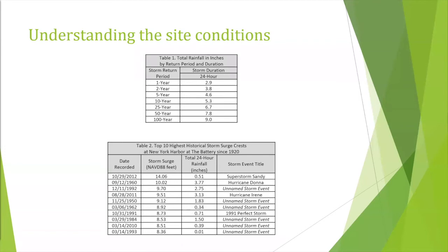So we understood that, but we also knew the price tag that goes along with that. They were talking about a 12-foot high wall around a 100-acre property with 8 different gates, which were floodgates. And then they were talking about putting in detention to hold 100-year rainfall, in addition to pumps, because if there is a storm event happening at this time, we've got to be able to pump it out. So we kept telling them that we didn't think that was the right strategy for the yard. And we were having trouble really connecting with them and getting them to understand that.